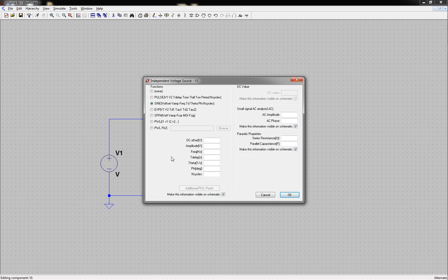Now I'm going to do just normal household voltages here in the United States, which for our household stuff is around 120 volts, or 110, 115, somewhere around in there. I'm going to pick 120. This is a single phase voltage. There is no DC offset, or at least we hope there isn't. There might be in reality, but you can play with that if you want to. Basically, that moves the sine wave up and down. But right now we're going to stick with 0 DC offset.